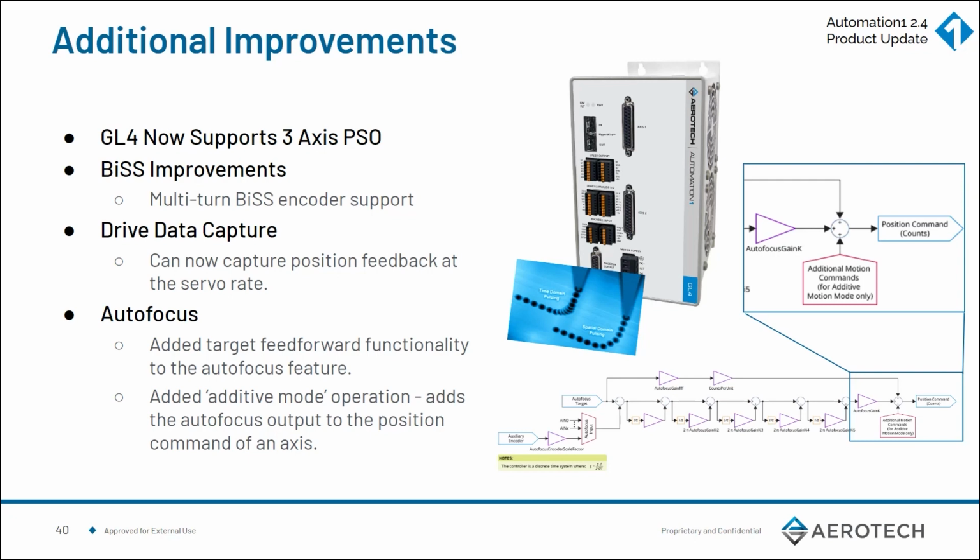It's also used in applications such as big science, synchrotrons, where you're actually using it to trigger data capture based upon position, not control an industrial laser. You can see from that image, when you're controlling the laser based on velocity, when you start to corner, your velocity changes significantly, and that laser pulse spacing starts to overlap. That leads to quality issues. Well, you don't want that. You want to know how many raw encoder counts have I actually traveled and control your laser based upon that.